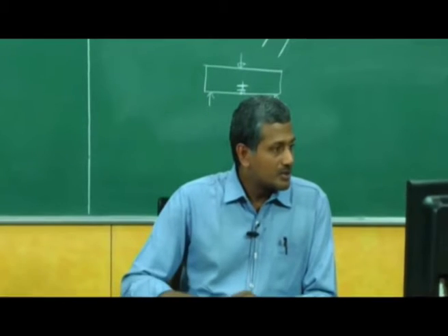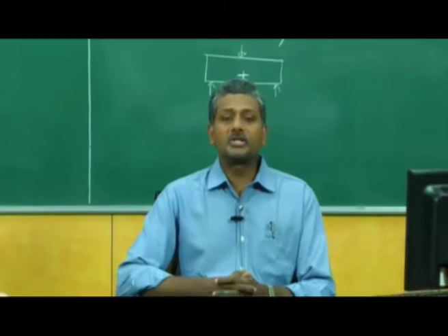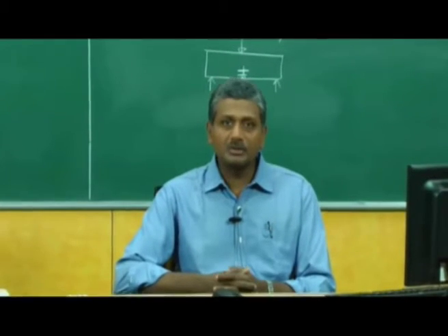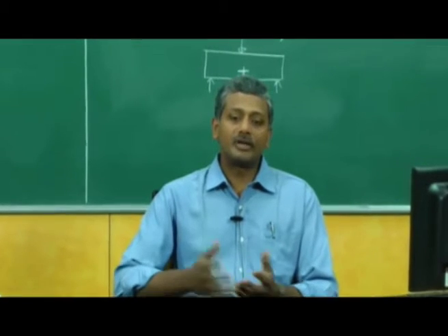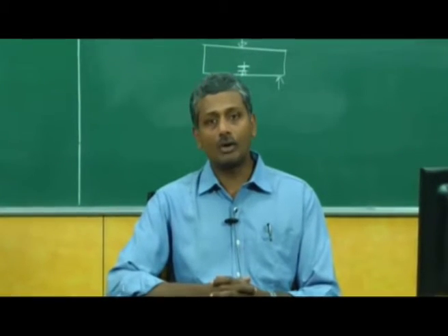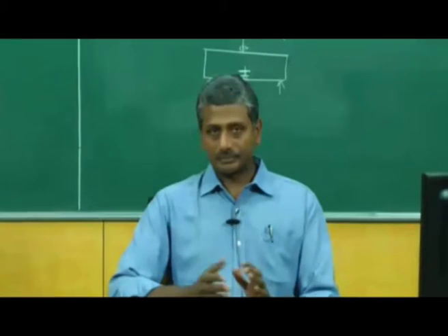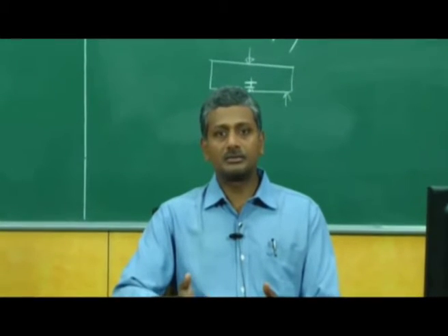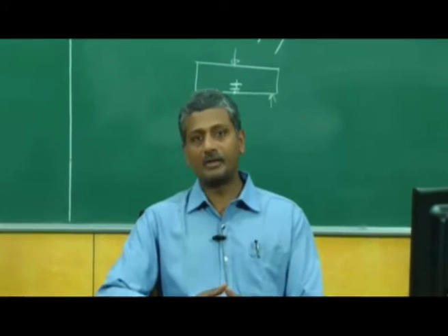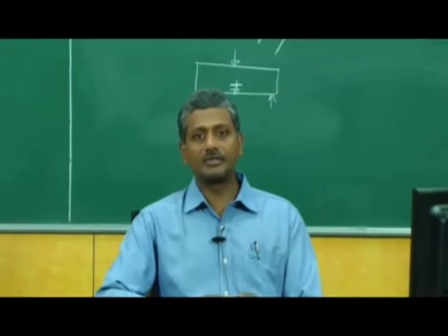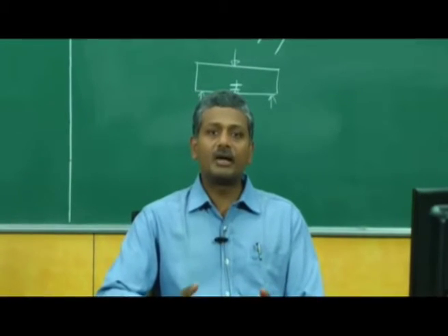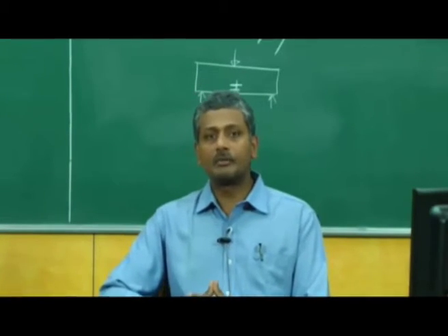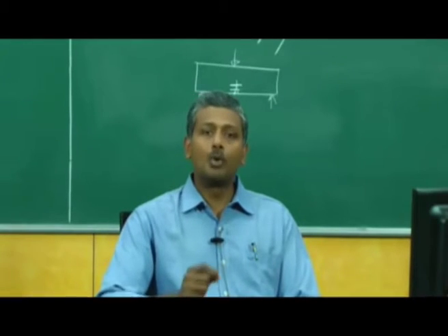Okay, so the question is, why is concrete strong in compression and weak in tension? Okay, now that's a very important question, and that basically is the fundamental characteristic of the concrete itself, that it's strong in compression and weak in tension. Again, to answer this, you must think back to the original discussion that we had about concrete being a two-phase material. Okay, you have your concrete, which is basically cement paste phase, in which you have aggregate phase that is getting dispersed. But what we also should remember is that concrete has a lot of pores in it.